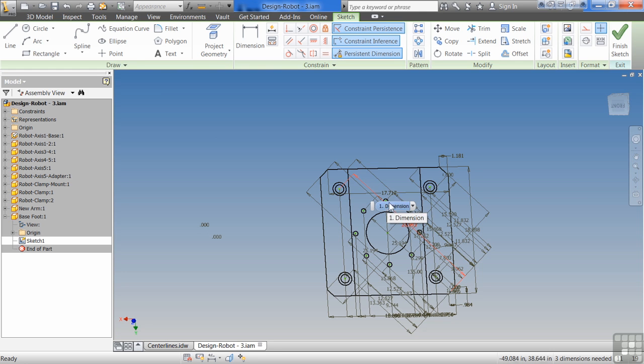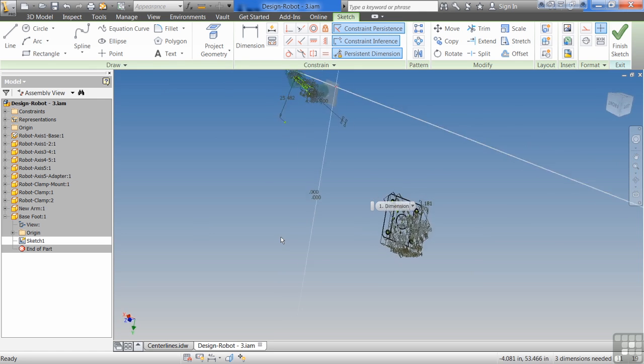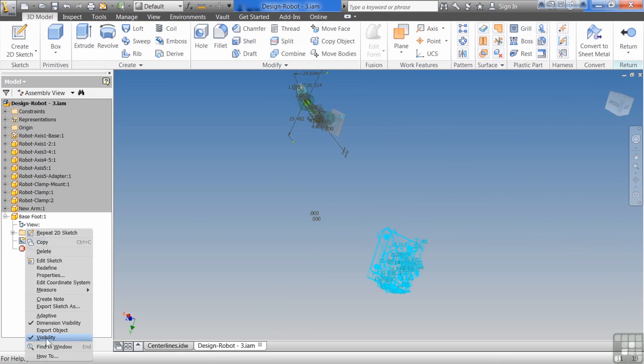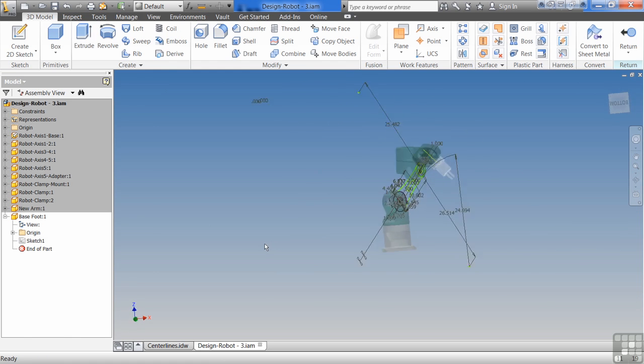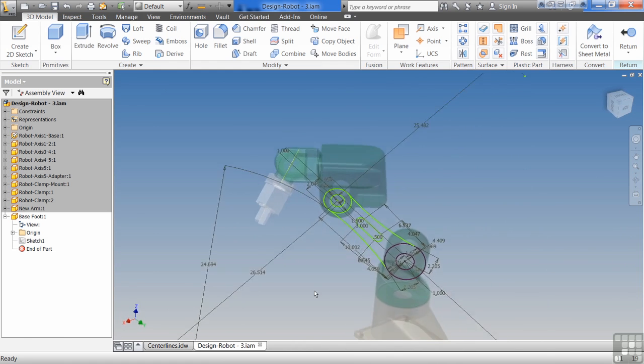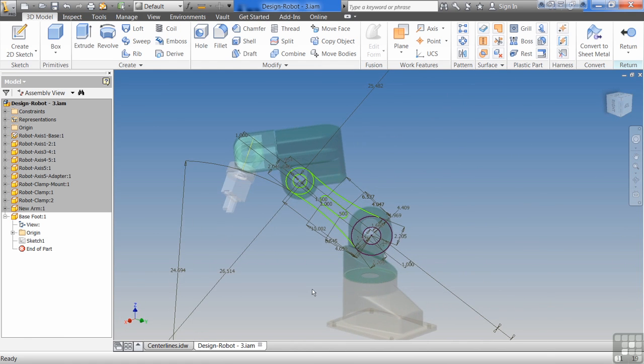So as you can see, importing AutoCAD files is very easy. You have a lot of control. Turn that back off there. And you can do a lot with them. Now, the biggest problem with them is they don't come over clean every time, so you do have to go through and constrain them. You may have to close some open profiles, depending on how bad the geometry was that was created with. I know these were closed good. It's just a matter of whenever the import happened, it didn't import them right. You would need to go through and basically flatten these out and close the profiles.